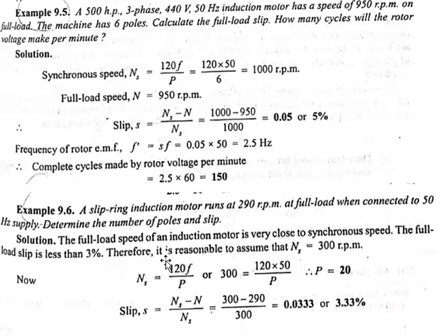There is a lack of information. The information is not complete here. Most of the time they may not ask such questions where there is a data deficiency. Here what you can do is assume the synchronous speed. See, 290 is the rotor speed, and we can take the nearest speed which gives a round figure. Means what? 290. What is the closest number? 300, and it is round. 290 and 300 is the probable or assumed value of the synchronous speed. You can assume and you can do the calculation, right?